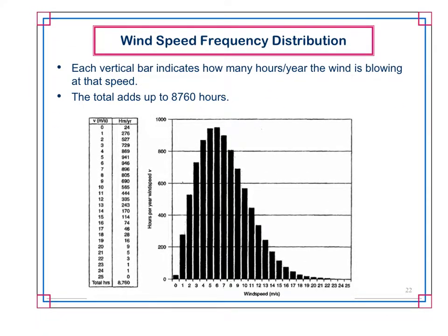So then we take the data that has been broken down by diurnal and peak, and we're going to reconfigure that, not on an average, but based on what a certain wind speed is and for how many hours it is at that particular wind speed. And so we're going to set up a distribution. So this is like a probability distribution, but we're going to do it with actual data, right?